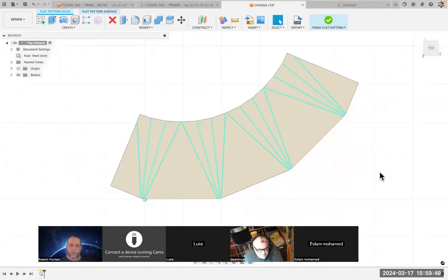So your cone comes out like two circles, if you made this all smooth, two circles with a common center to make a cone. Well, it's got a flat bottom, so it's not like a normal cone, but close to a cone. Anyhow, that is our flat pattern for that fancy piece of geometry. And then again, we have our export if we need to get it out as a DXF for whatever use after here.